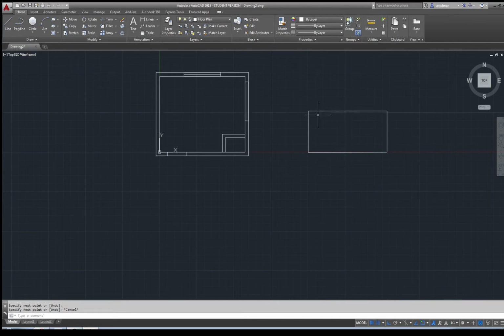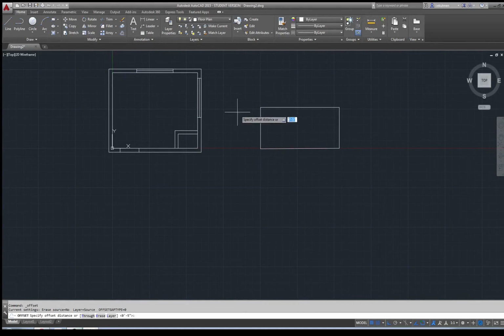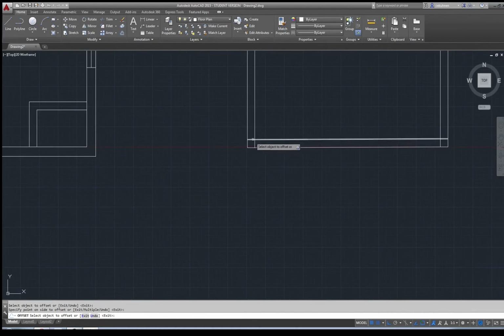Okay, so see, with my mouse I can highlight two different objects. I go to offset and say 5 inches. You see they're not all perfectly offset at the same time together. I would have to trim those interior lines out, which is not really good.